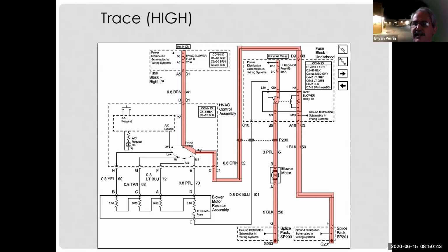Not so surprised. If they don't connect, how can they have 12 volts? Because they're connected to the circuit on this side, but they're open on this side. So they're connected here, right? If I feed power in here, power is going to feed back all the way to here, and it's going to feed back all the way through here. It just can't complete a circuit.